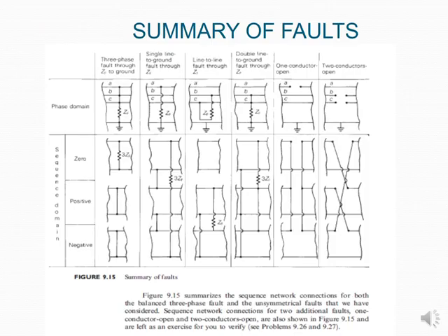Then this is the summary of all the faults that we're looking at, and you can see that on the top I've named all of them, the shunt as well as the series type faults, and it really shows what would happen if you had a ZF present. Okay, so when they go to ground, they go via another impedance to ground, so it would be a star connection type of fault. And you can see what our zero, positive and negative phase sequence impedances would be looking like.